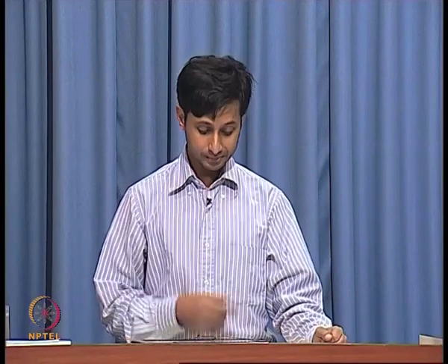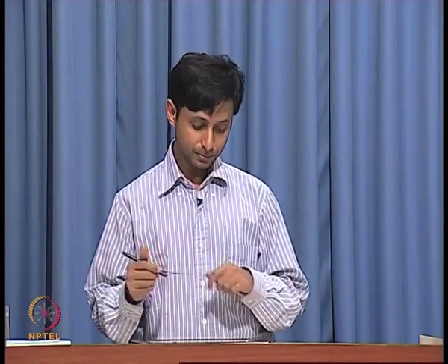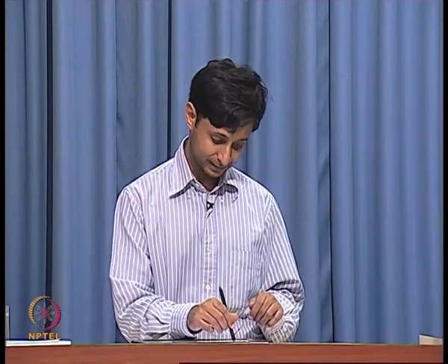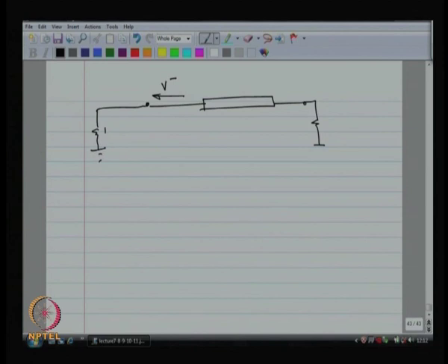So, V minus adds on to that voltage. The new wave which is moving backwards adds on to the old wave. The old wave is still present over there, right. So, if you do use superposition, then you can ignore the fact that V plus was there, you can ignore the fact that I launched a wave to start with, and you can just consider that you have got V minus, a wave coming backwards, it hits R s, and then what is going to happen? It is the same situation as before, the one we just computed.